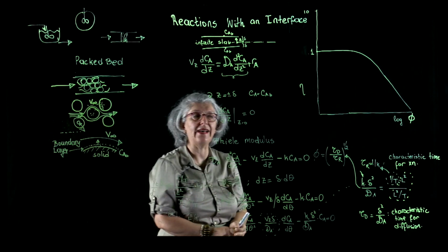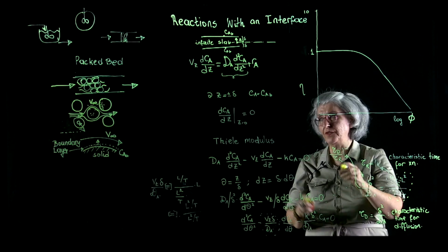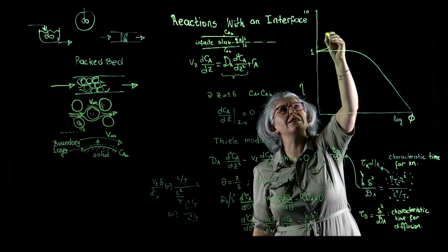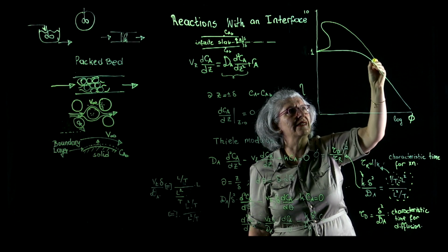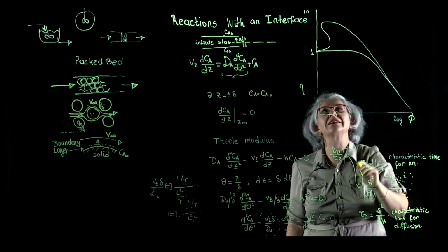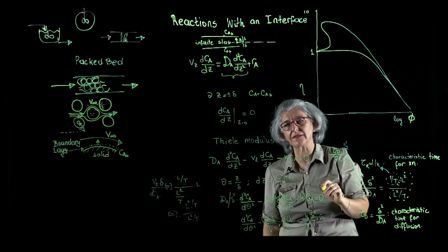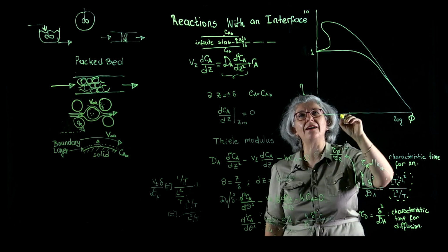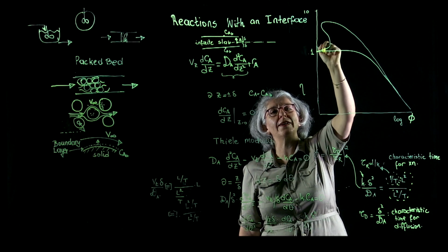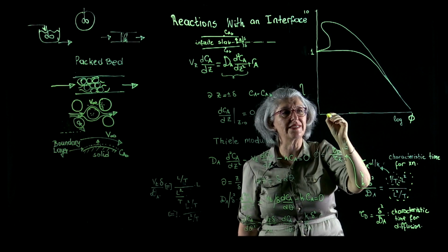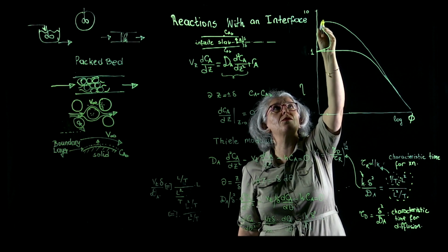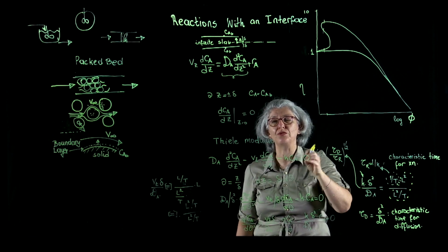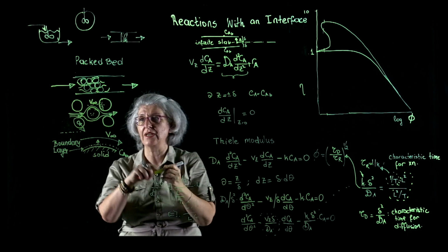But when we have problems of heat transfer in the catalyst domain, we might have situations that give very strange results, that our effectiveness factor exhibits multiplicities, that we have multiple values of effectiveness factors for the same Thiele parameter, 1, 2, 3.